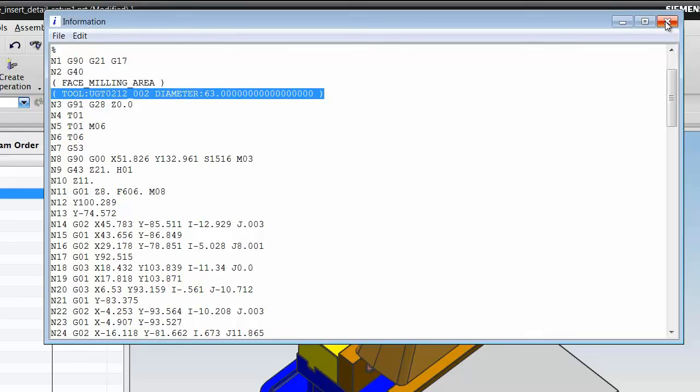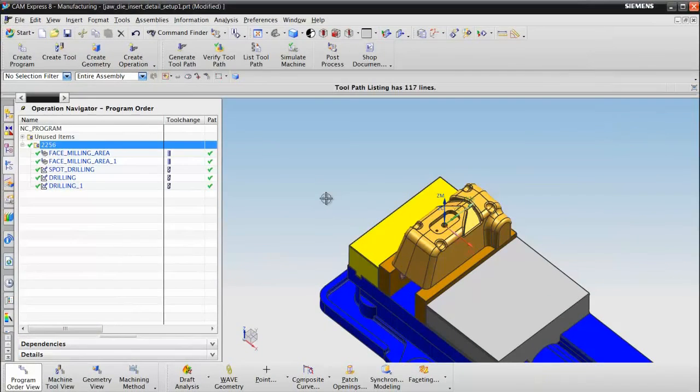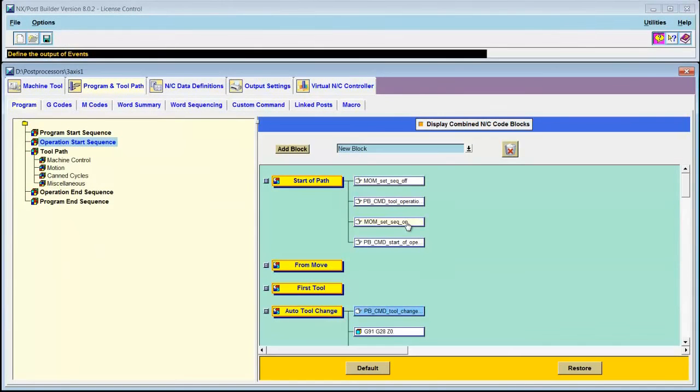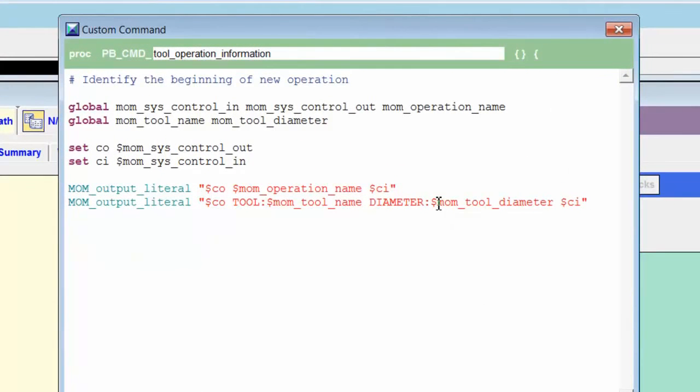We can fix that using the TCL command called format. Use square braces to indicate a new command being used within an existing command. Left square brace, format statement.